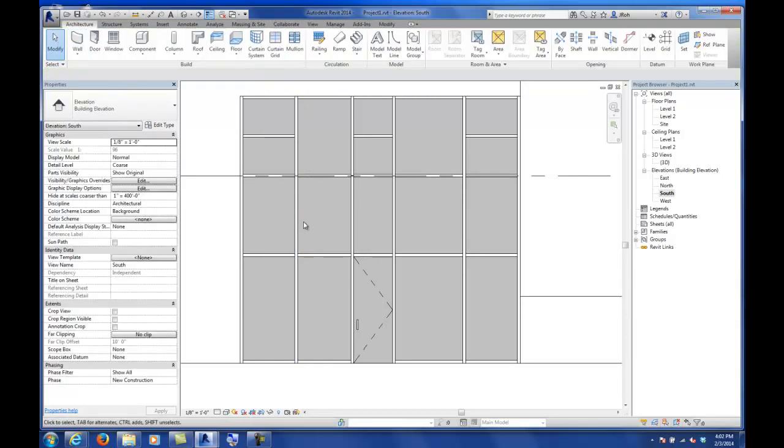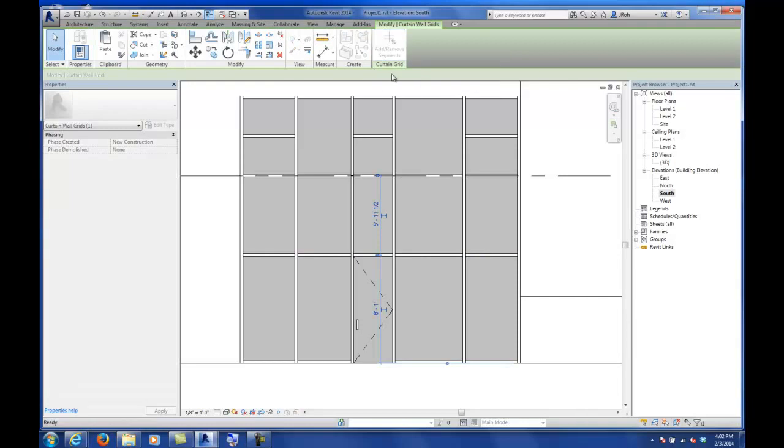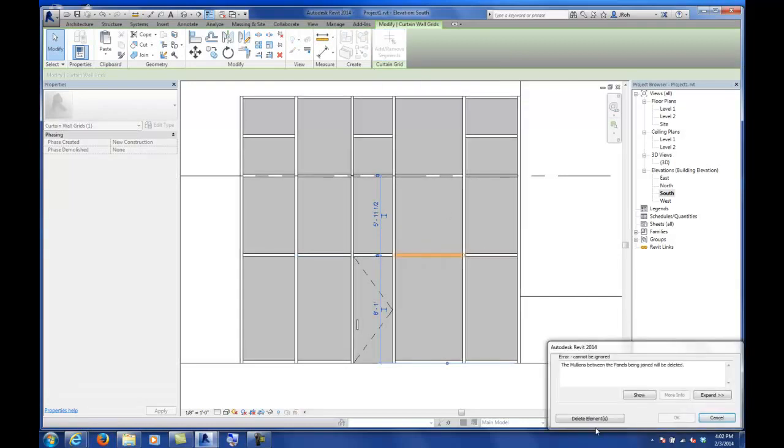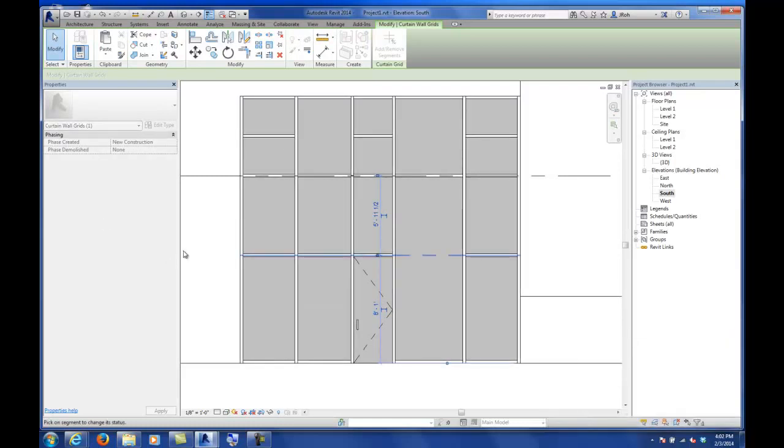You can also do that at any time by tabbing over. So I'll tab over this other horizontal one, and I can add and remove segments at any time. And sometimes if you have a mullion that's assigned to that, it just wants you to delete it, and you can start to carve out and make different designs part of your mullion assembly.